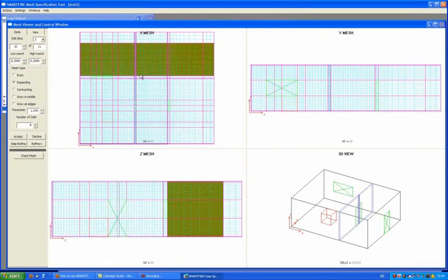Remember now that we're not seeing just the region that we defined earlier and the geometry that we entered, we're also seeing the extended regions. So we have the extended regions to control in terms of mesh budgets as well.